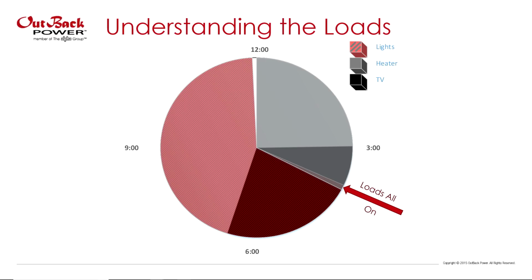So understanding, will we need this energy over a short amount of time or will we need this energy over a long period of time? Because how fast lead acid batteries are discharged will affect your battery capacity, and we'll go over that later. The real world scenario won't be so easy because I got to control all of the variables. This is a little bit easier for me. It really just depends on the customer and understanding your customer and really understanding what the worst case would be.